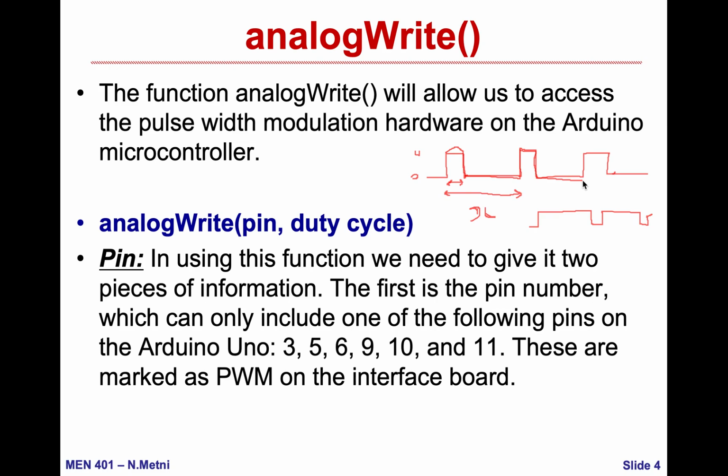Consider a flying drone that is a quadrotor, so it has four rotors, four motors. I need to output four different PWM signals and at the same time read from the accelerometer, the inertial navigation system, the gyroscope, the altitude sensor, and then do the autopilot with closed-loop control. So it's really impractical to keep the CPU busy just outputting a PWM.